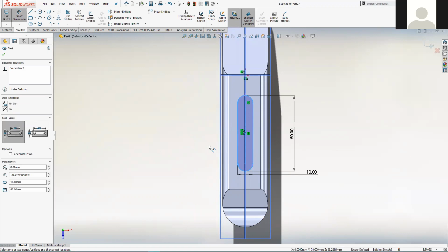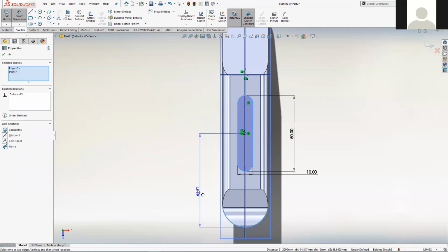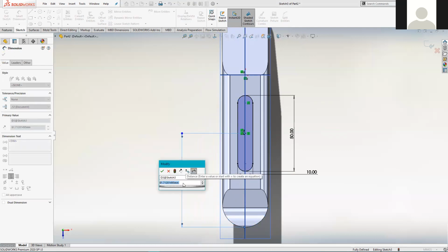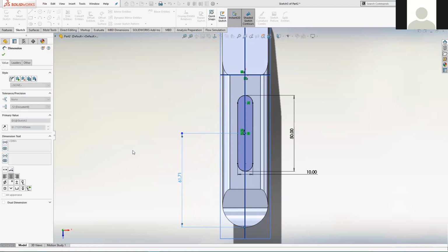Then we'll start to hold Shift down before we click on the arc. And then you can see, as I hover over the arc, the dimension there is the one to the outer surface of the arc, rather than to the center point that marks the center of that semicircle, essentially. So 60 millimeters for that one.